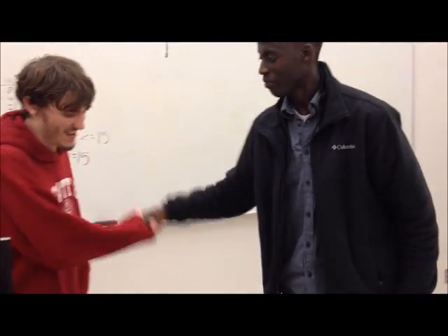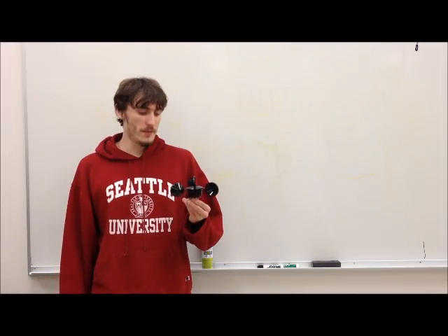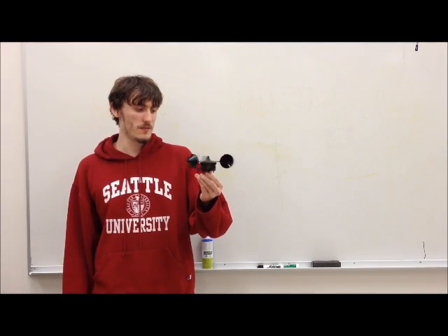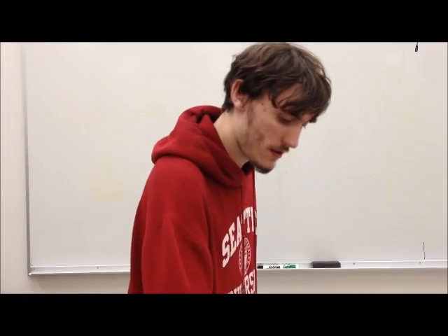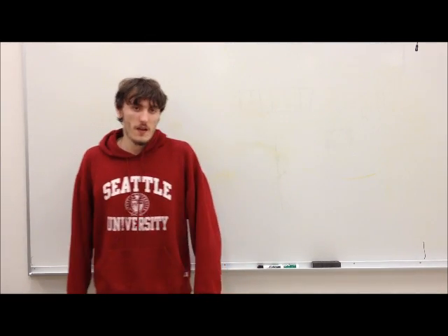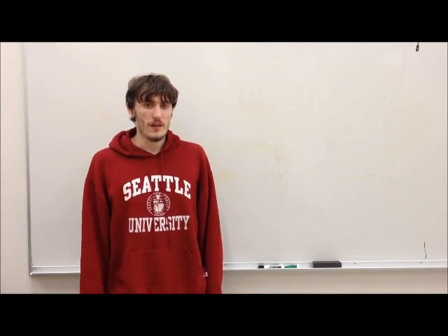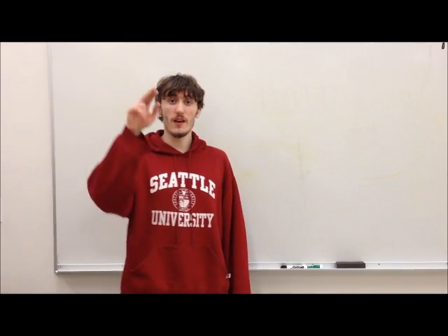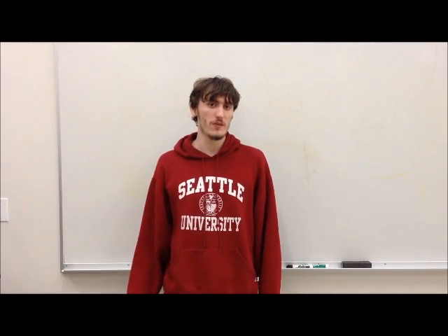Very good job. This is our team's cup anemometer. When the wind blows, it spins and it gives us a square wave. By looking at the square wave with our Fez Cobra 2 board, we can measure when the pulses go high and when they go low to determine the frequency of the signal.